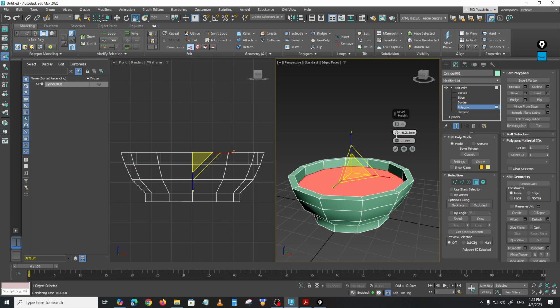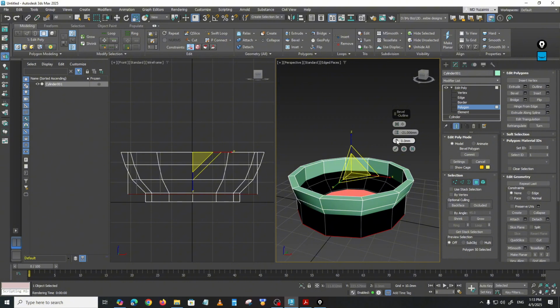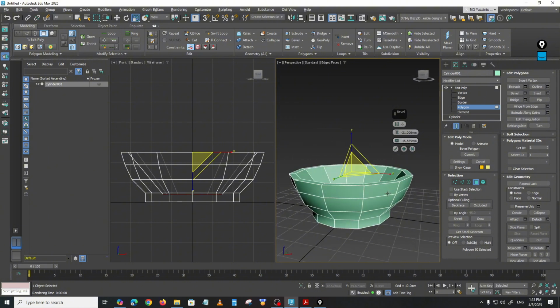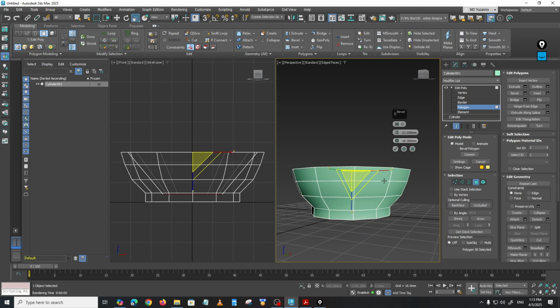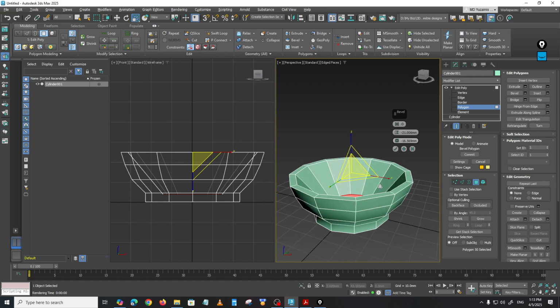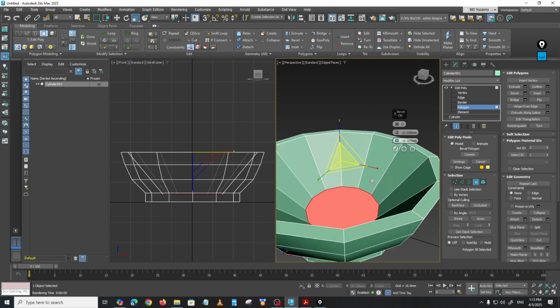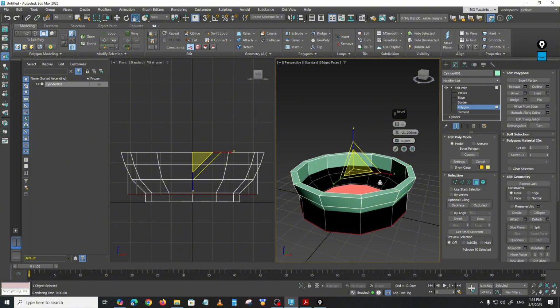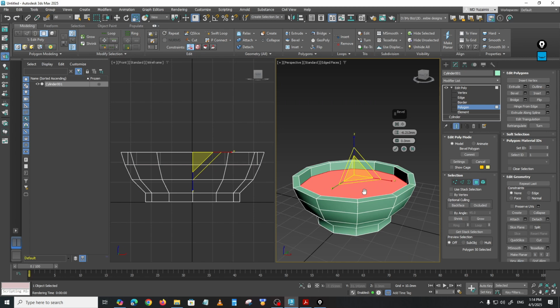So I'm not going to extrude all the way down and then decrease the size like this. That is not really effective, because you see on the outer there are a few horizontal loops to create the shape. This one is only one going down there. It's not really a good way to do it. So you need to follow the one outside there, unless the shape is really like this, like you intended it to be like this. But in this case it's not. I'm going to undo, Ctrl Z.